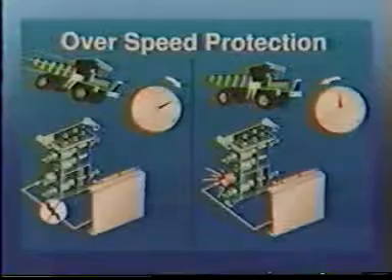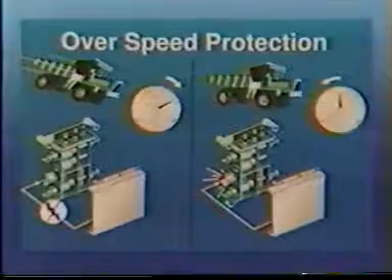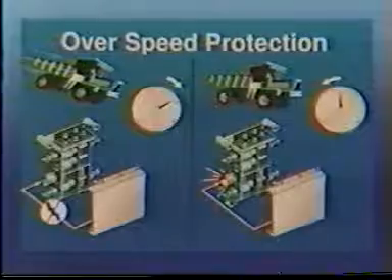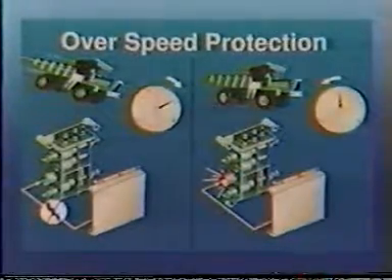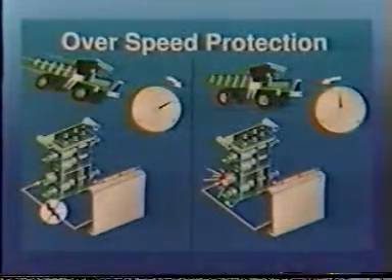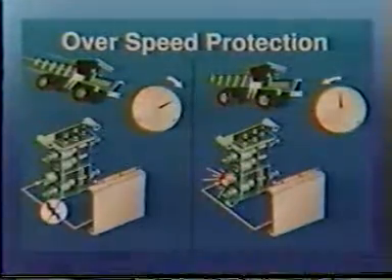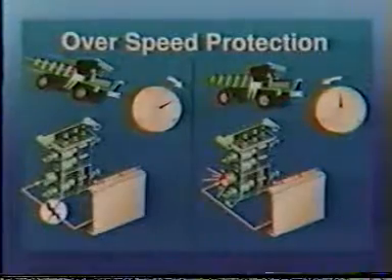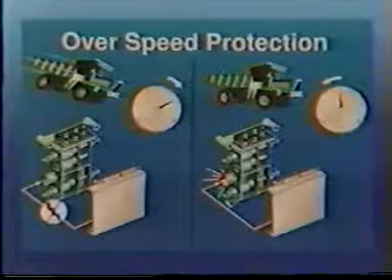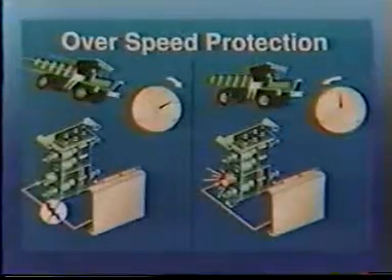If the engine speed exceeds a predetermined RPM, the ECM will remove power from the fuel shutdown solenoid valve, stopping fuel flow to the system. It will also log a fault and continue recording engine data. When the engine speed drops to a predetermined RPM, the ECM will apply power to the shutdown solenoid to restart the engine. The ECM can be programmed to deny engine restart if a predetermined number of shutdowns has occurred. This prevents the use of the engine when an intermittent problem exists.